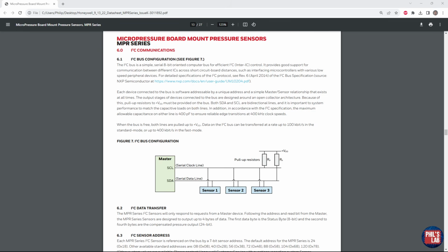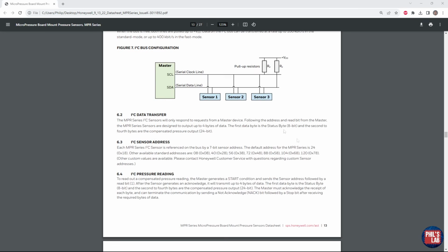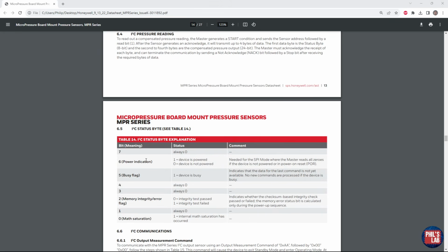Another big part of datasheets is not just to help you with the hardware, but also with the firmware implementation. Of course, this depends on the device, but for example, for a microcontroller or sensors such as this, which has digital interfaces such as I2C and SPI, once you have the hardware in place, of course, you're going to have to make this work, so to speak, with a microcontroller, processor, and so on. And these datasheets will help you do that. Not only will they tell you how to hook up the communication channels, but they will also tell you about, for example, register contents. So this will typically be near the middle or end of a datasheet.